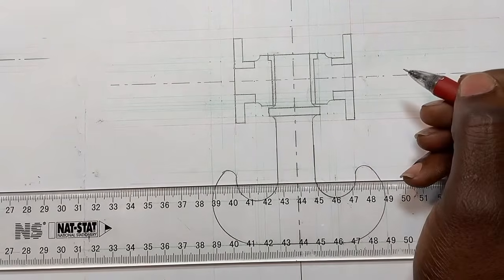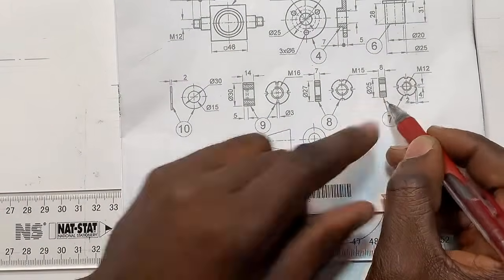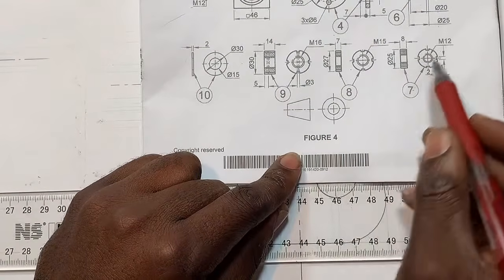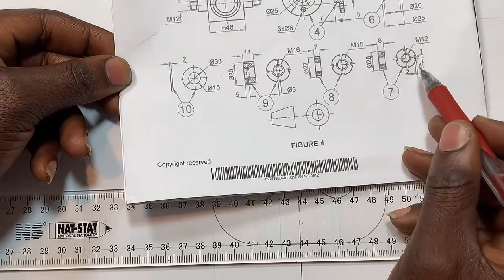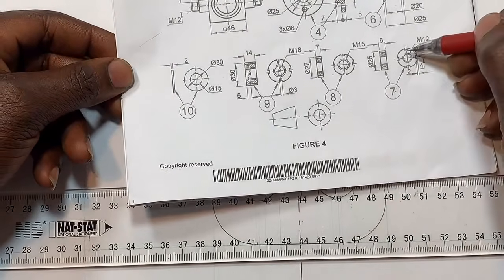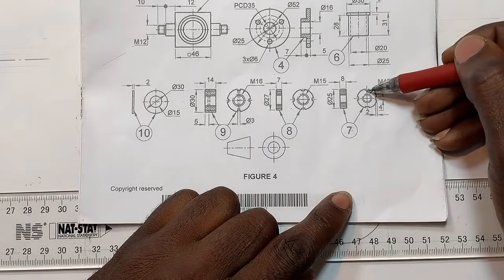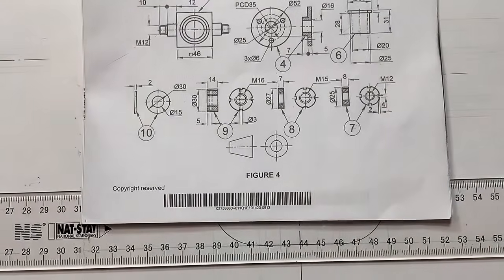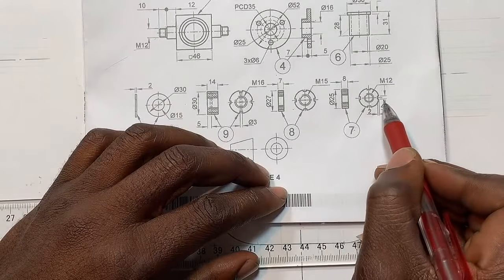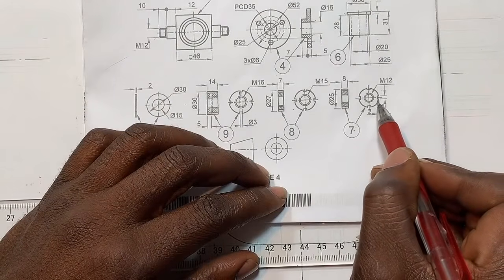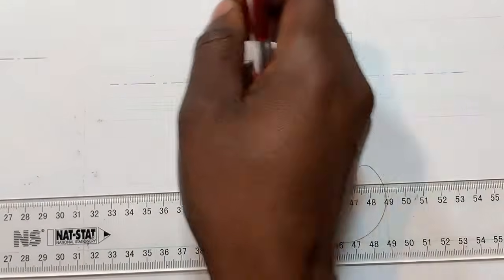So now how are we going to draw this nut? So we will draw this one, not this one. Remember, that's given according to first angle orthographic projection, which is going to consider the front, not the left. And double check, if we put the cutting plane, from here till here the hex won't be cutting, and it will start to cut from here. However, we are given the front view in section already, so it's of a thickness of 2 millimeter. So from here till here is 2 millimeter. So from here going down, we're going to record 2 millimeter.